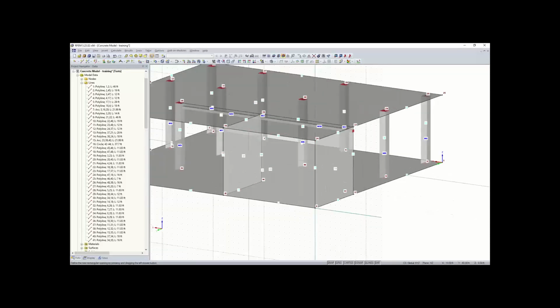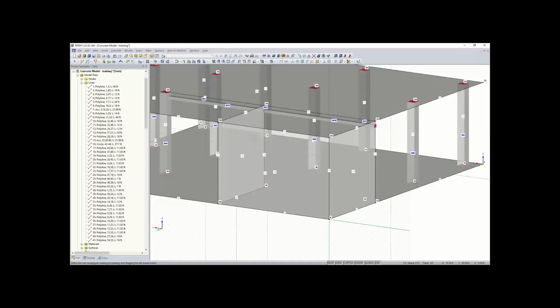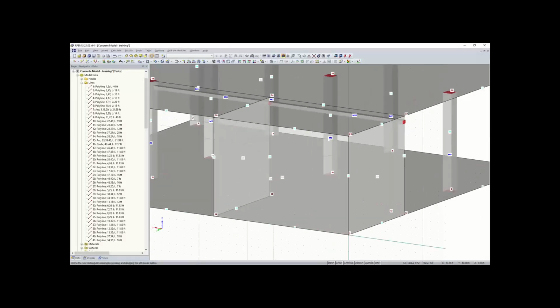And now we can draw our rectangular opening. That's going to start at the top left here, at the coordinates 1408. We can snap to grid points right here, and then we can just simply draw that.